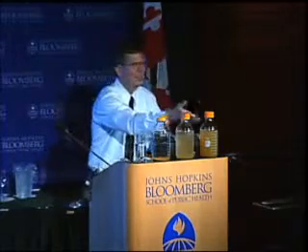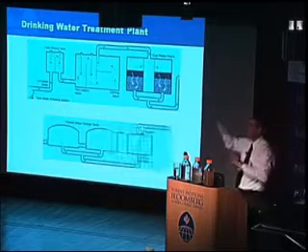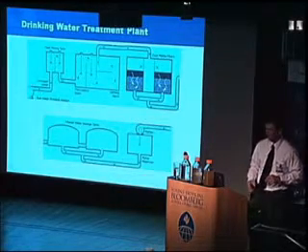So what we have here is this gelatinous mass that forms a floc that slowly settles out that then has clear water. Traps the particles, removes the microorganisms. But we don't stop there. We then filter the water through large filters. We then treat the water with chlorine, and finally go to those thousands of miles of distribution systems.